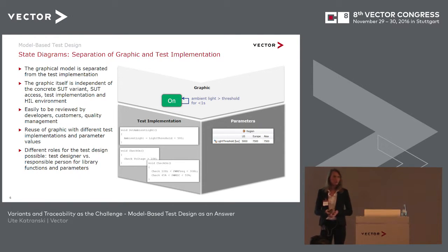And another advantage is that I can separate roles. The test designer, who is responsible for the graphic, is not necessarily the same person who does the HIL or the person who is responsible for the ECU parameter threshold values. So that was one model-based approach as to how we can create test cases.